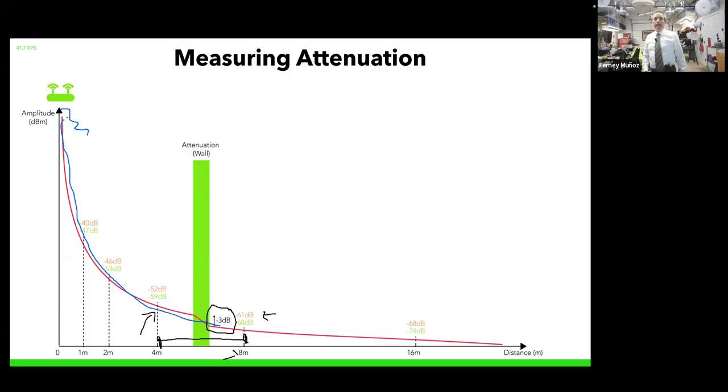Yeah. And then the next day they show me, look, everything is gone. There's nothing. So those waves are just going to travel freely throughout the warehouse. Then the next day it was filled up to the ceiling with 2-liter plastic bottles. What are waves going to do through that? And what's the attenuation index? I don't know. You're going to have to go measure. It's just waves, it's just energy, and it goes through the laws of physics. If it's open space, it will attenuate at that rate. Double the distance, quarter the power. Double the distance, quarter the power, or minus 6 dB all the time.